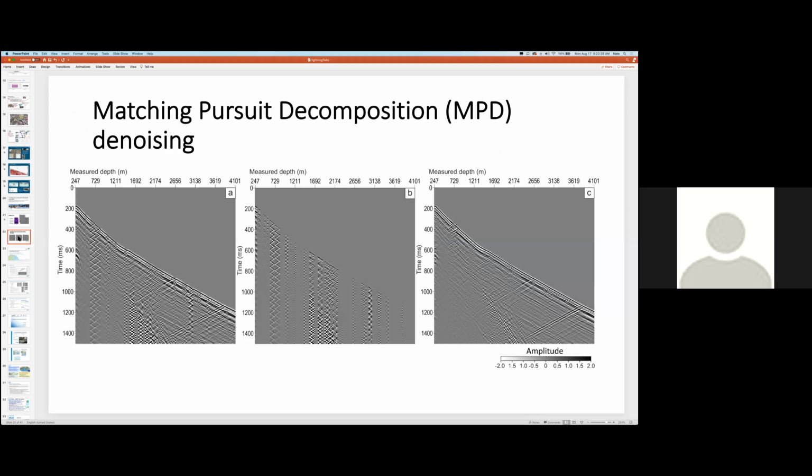And we suggested to use matching pursuit decomposition of Gabor atoms for noise characterization and suppression. On plot A, we will see the input signal, on panel A, that we were trying to represent as a weighted sum of Gabor functions. And by analyzing the statistics of the noise, we're able to identify the noise parts of the signal representing the lapping of the cable on panel B.